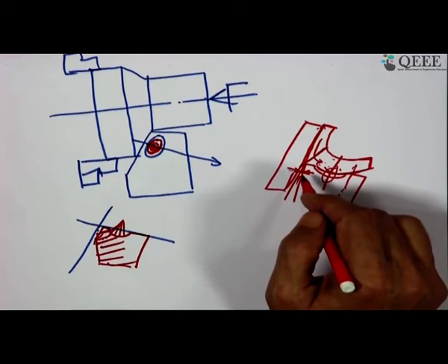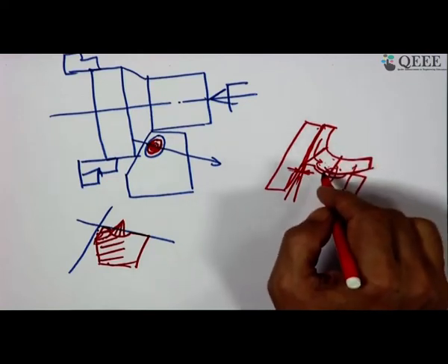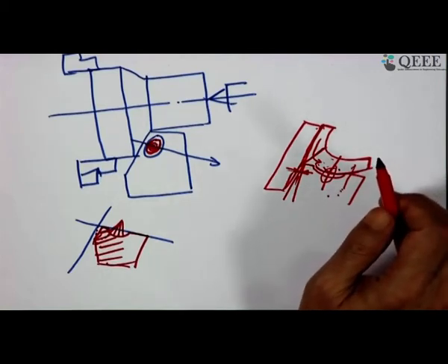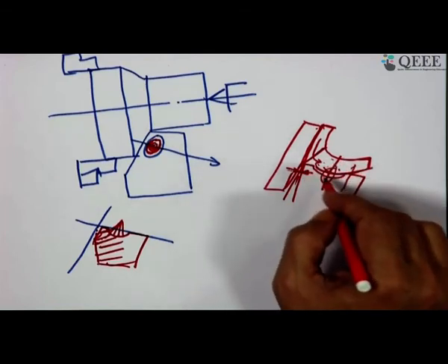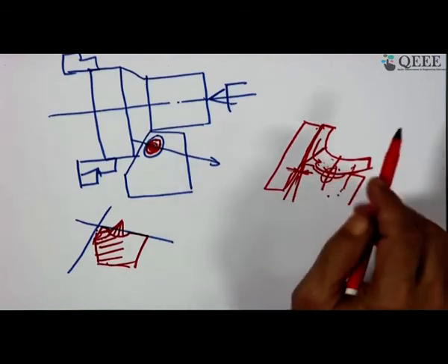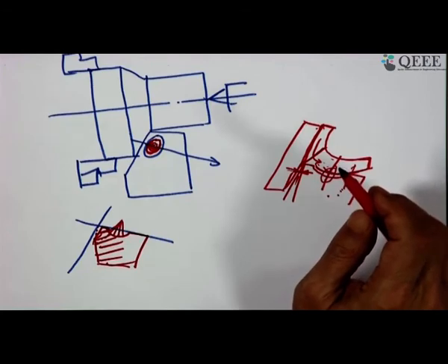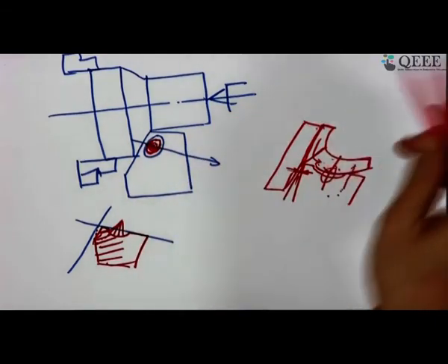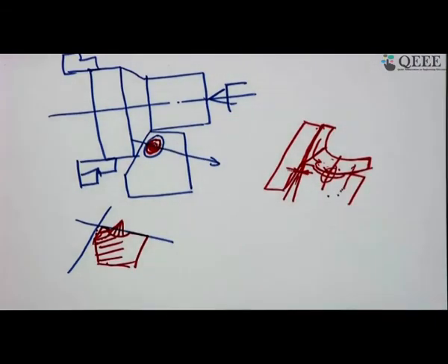So, that temperature, what is the expected temperature, one has to ascertain, one has to make a fair estimate or calculation or measurement, and then only can we predict what kind of tool material or coating material we can put on that side to combat the wear, and on that active surface of the tool, whether it is the face or flank of the tool, that is more resistant to such kind of chemical nature of wear.